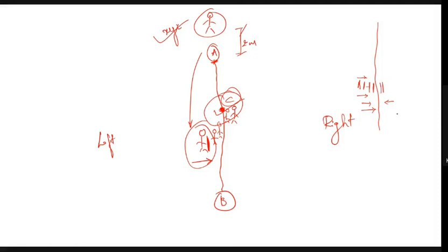He will come here. Move a little bit towards the left, so he will come to this point. So the person will say place the ranging rod at this point. This is how station C is established.